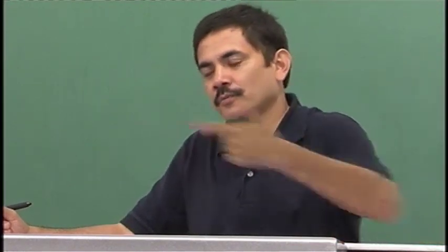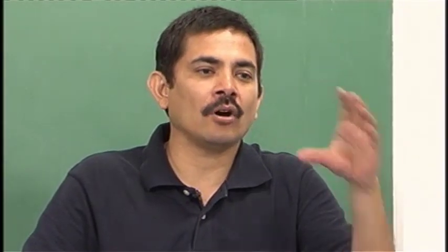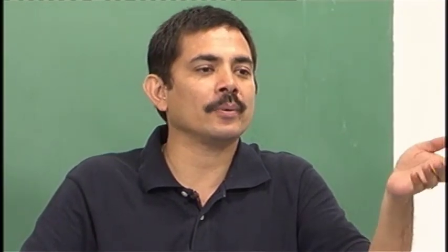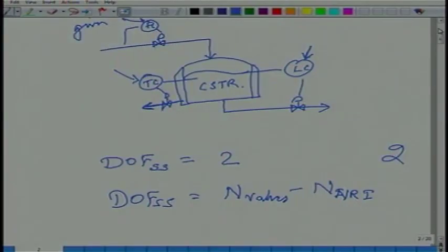Do you see what I am saying? Because that is what gives you the maximum conversion. Yes or no? So, I am counting it as a degree of freedom, but in practice the reactor is operated, or gas phase reactors are operated at the highest possible design pressure. Do you see what I am saying? Similarly, if I go back to my CSTR example, in the CSTR we said that the level inside the reactor affects the conversion. Yeah, if I am operating at a low level, conversion will be lower. If I am operating at a higher level, conversion will be higher. Yeah.